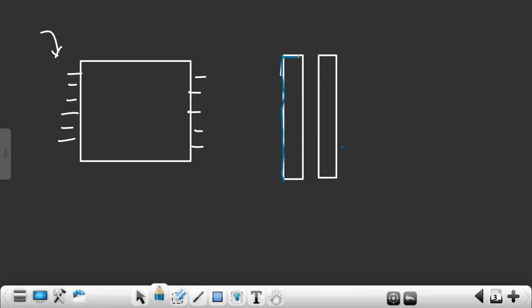So during fabrication, what may happen is the metal layers will bulge like this at some areas because of improper cutting of metal layers. Even this layer may bulge, right? So these two metal layers get shorted. They are shorted during fabrication. Due to variation in fabrication, they may get shorted, which the foundry can't identify whether they are shorted or not.